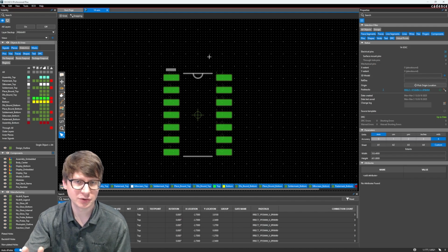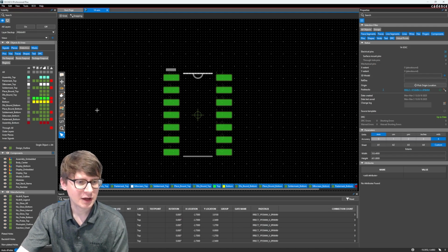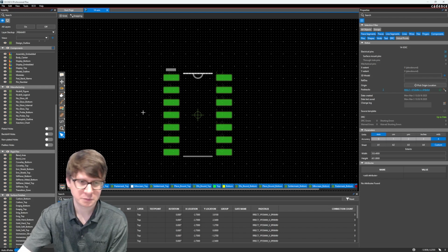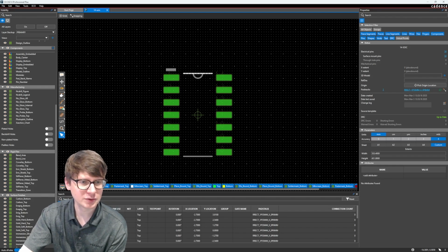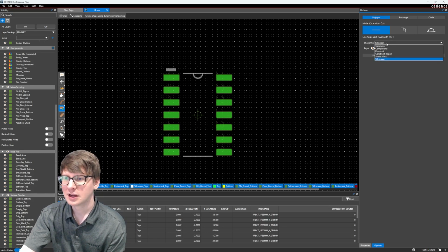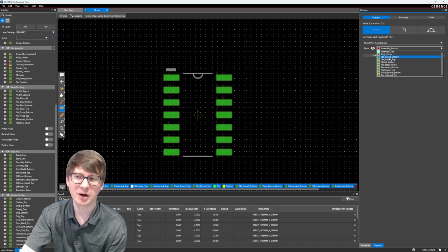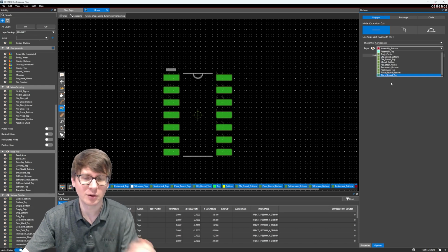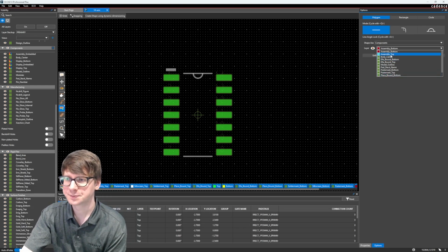Let's go ahead and add our 2 mechanical layers, which are the assembly layer and also the DFA layer. So to do that, I'm going to use our rectangle command, except this time I just want it to be a polygon, not filled. And if we go into components, you'll notice that we have this assembly top and bottom layer. And if we scroll down, we have this place bound top and bottom, as well as the DFA top and bottom. So those are, sorry, not the 4 layers, but the 6 layers, or 3 layers if you only care about the top, that we need to set here.